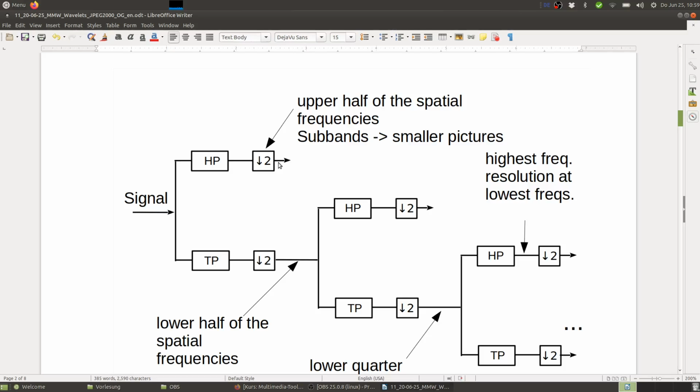We don't want to spread edges out because that would make them look blurry, right? So this avoids blurriness, and this is also one of the causes of the blocking artifacts when you have the DCT. Even the high frequencies have the downsampling factor by 8, and basically those edges will be spread out and they become then blocky. So this is something that avoids this blockiness by using this tree structure, because you have a higher spatial resolution for high frequencies which appear around edges.